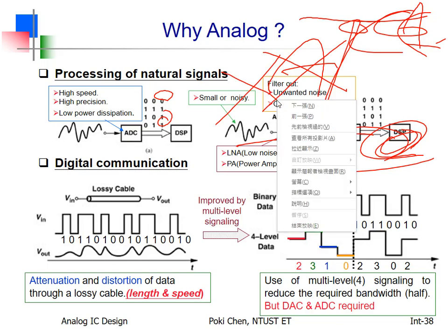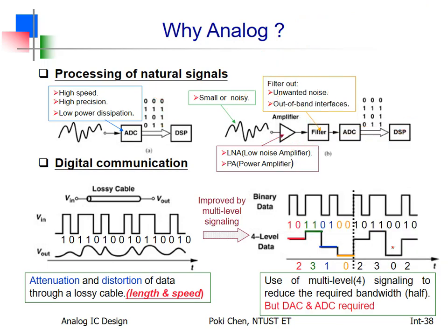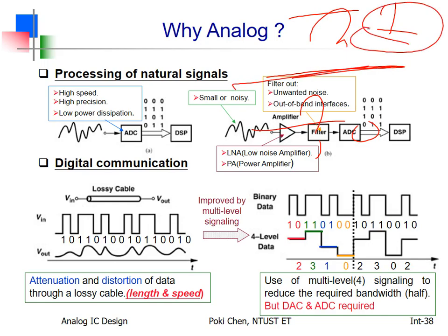Yeah. Maybe you can say, hey, in their world, for the real signal, they do not have only 0 and 1, right? So they have a very easy rule to differentiate between 0 and 1. They have the so-called threshold voltage. Above it, that is 1. Below it, that is 0. That's it. Okay? So never mind what's here, what's there. If it is above the threshold, all of those will be 1s.